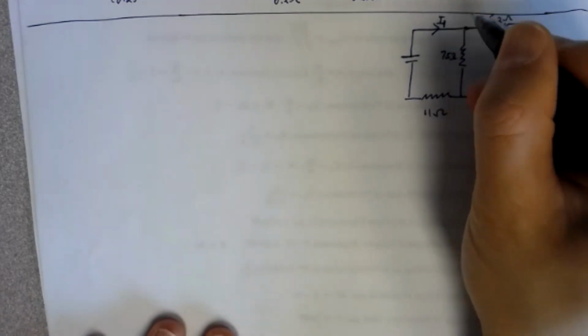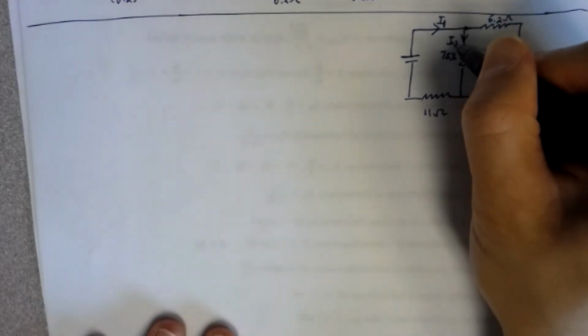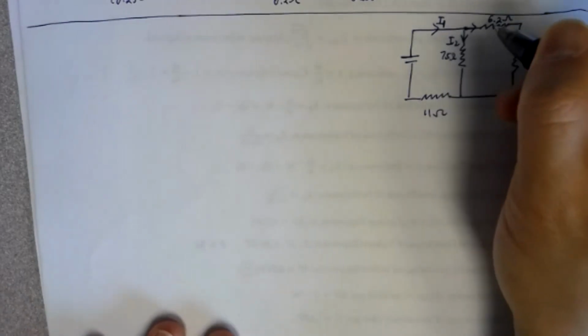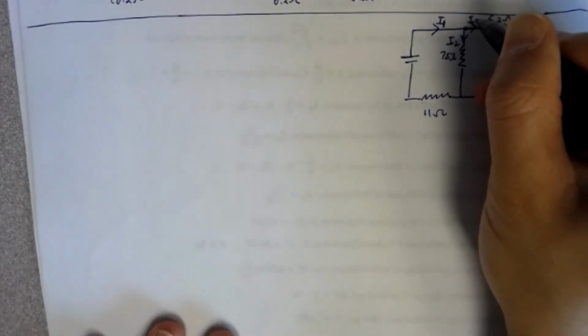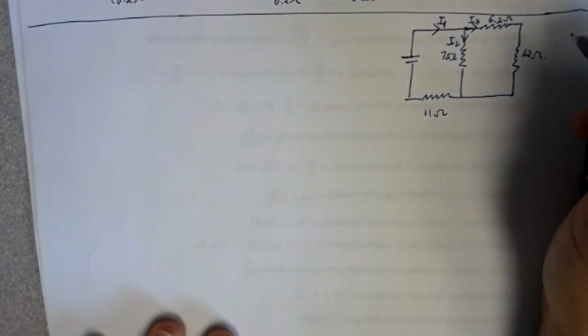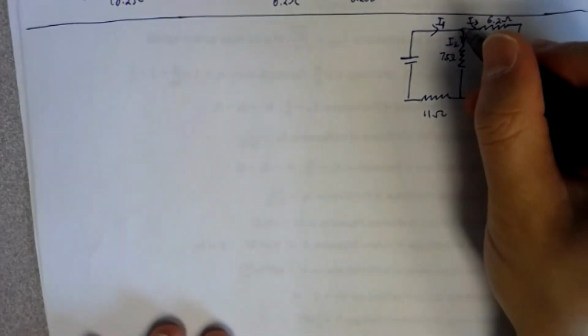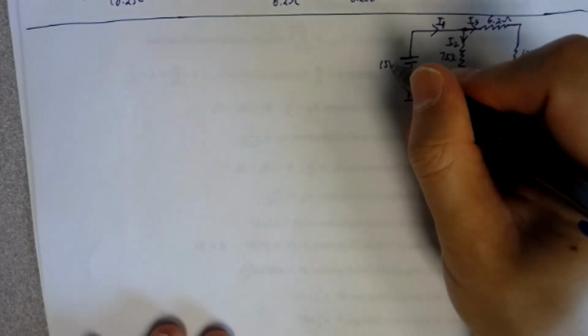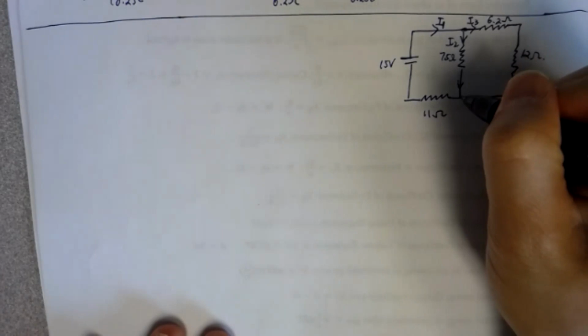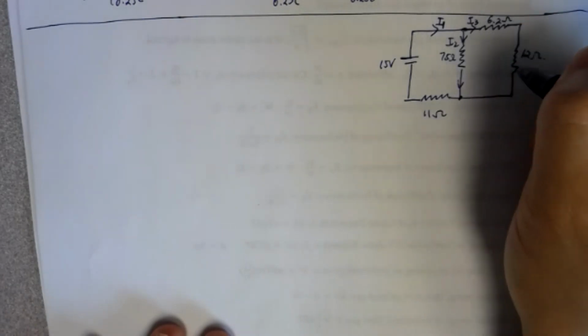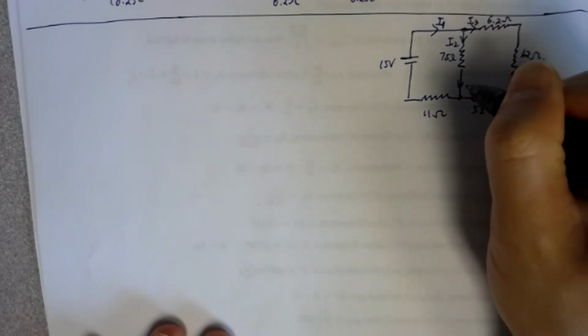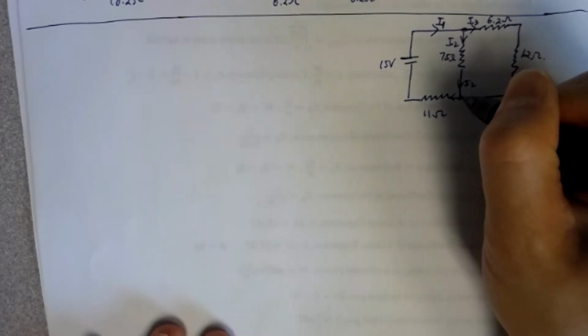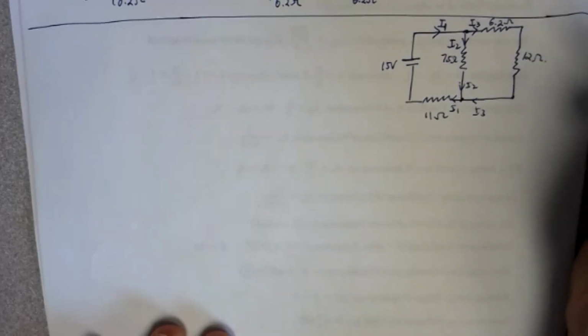All right, so there will be this current. Let me now just call it I1, because this I1 will split into two. This is I2, and this is I3. So at this junction, you can see the current. This battery is 15 volts. The current I2 will go into this one, and then I3 goes through these two and comes here. I3 and I2 will merge, right? The two will merge, and now it becomes I1 again.